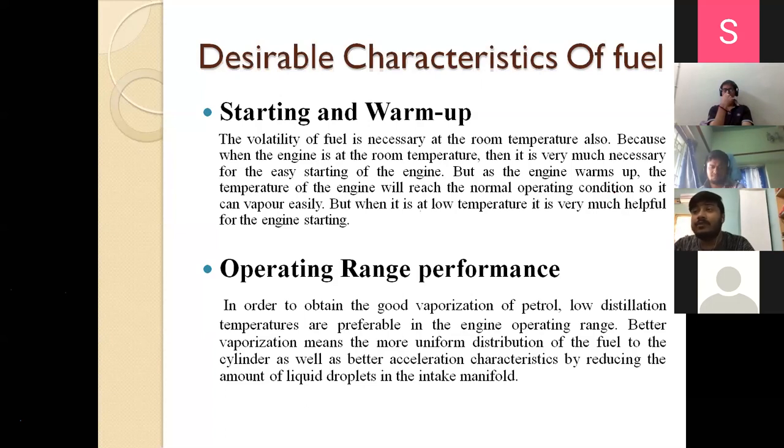So if the fuel is not volatile enough to go to the cylinder and run the engine smoothly, it will not be easy for the engine to start. That means the fuel must be volatile at room temperature so that the engine can start smoothly. Clear? But what happens whenever the engine starts?